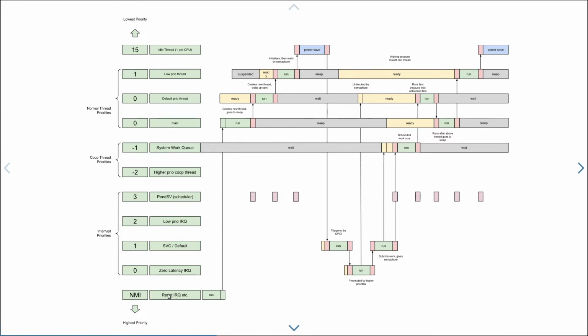The reset interrupt is basically what happens when your CPU starts, and that's actually an interrupt handler. The CPU is going to execute this interrupt handler, and then this interrupt handler in turn sets up all of the tasks and eventually executes main. Now, in an RTOS concept, you will be going into main, and this is actually going to be a separate thread with its own stack that will then continue the init process and create other threads and set up the rest of the application.